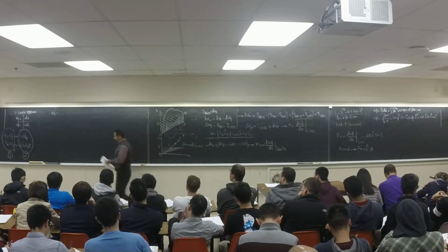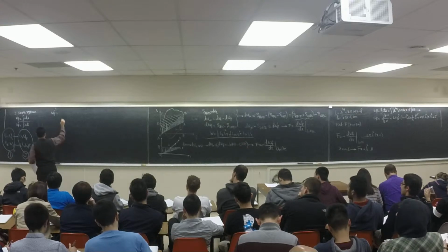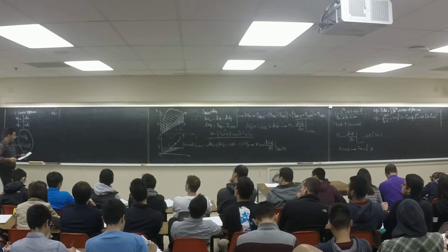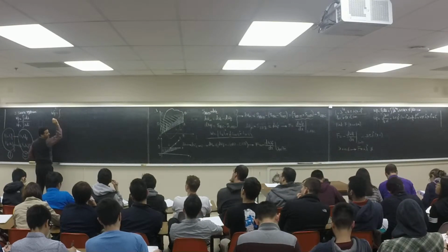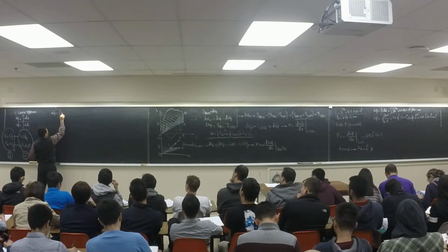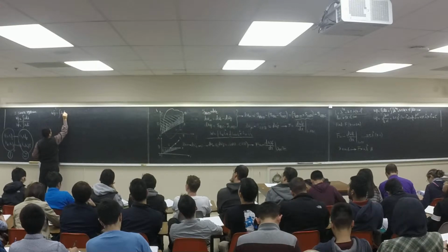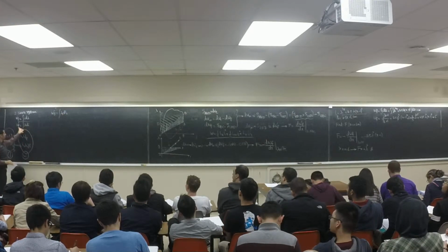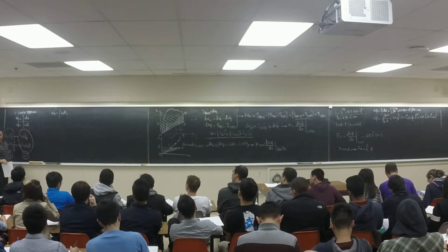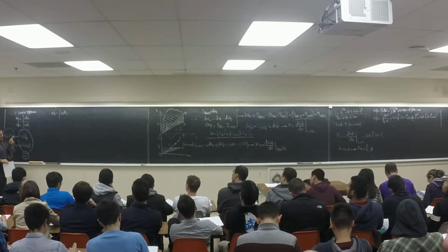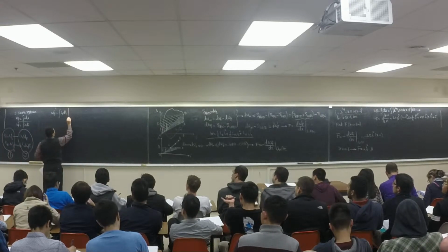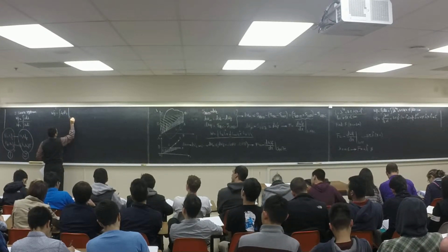Now, I'm going to put it this way. So, I'm going to say W'_f is equal to the integral of λ1 di1. This is the path I'm going to select. Remember, the co-energy is this one, right? λ di, right? λ1 di1 when i2 is equal to 0.